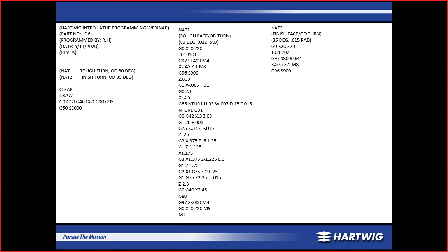Then we're going to turn constant cutting speed on to 900 surface feet per minute again. Rapid to Z0 this time because we want to finish the part to length. G1 X minus 30 thousandths this time because I want to go double my nose radius. Rapid to 100 thousandths off the end of my part. And I'm rapiding this time to the start point of my finish shape.